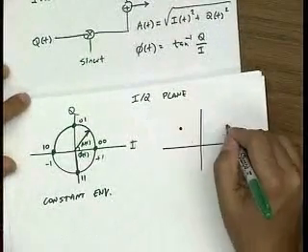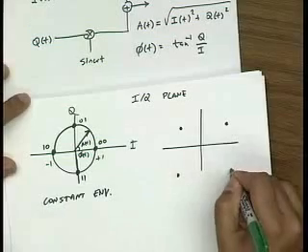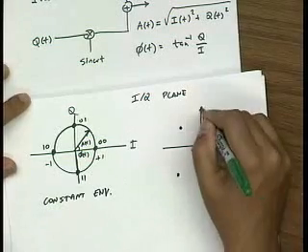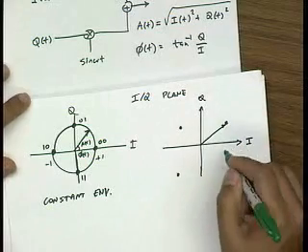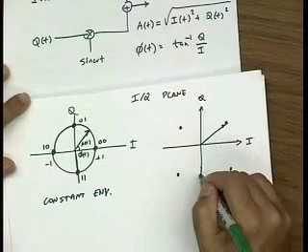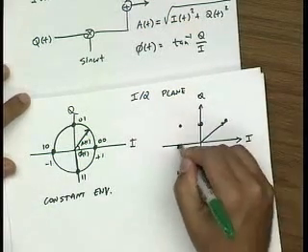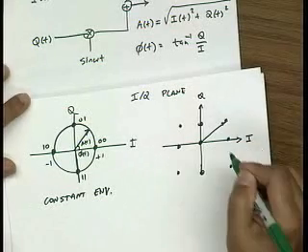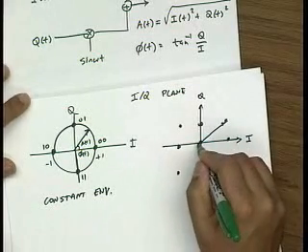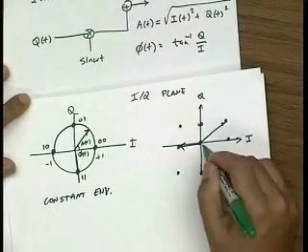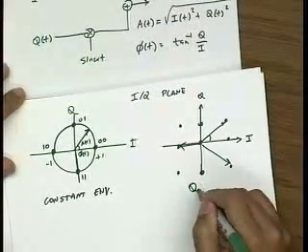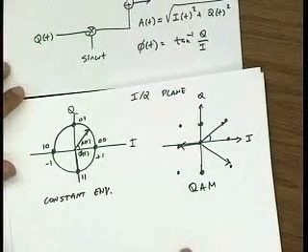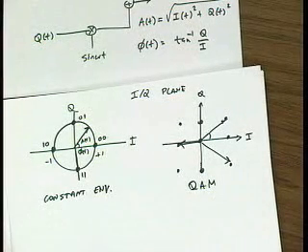For instance, I could send these 4 points on the IQ plane, and now you could see that the amplitude also changes. For instance, let me add some more points to try to pack more information. So you could see that now the envelope changes depending on what bit I send, and so does the phase. Okay? So this would be in general what's called a QAM modulation scheme.